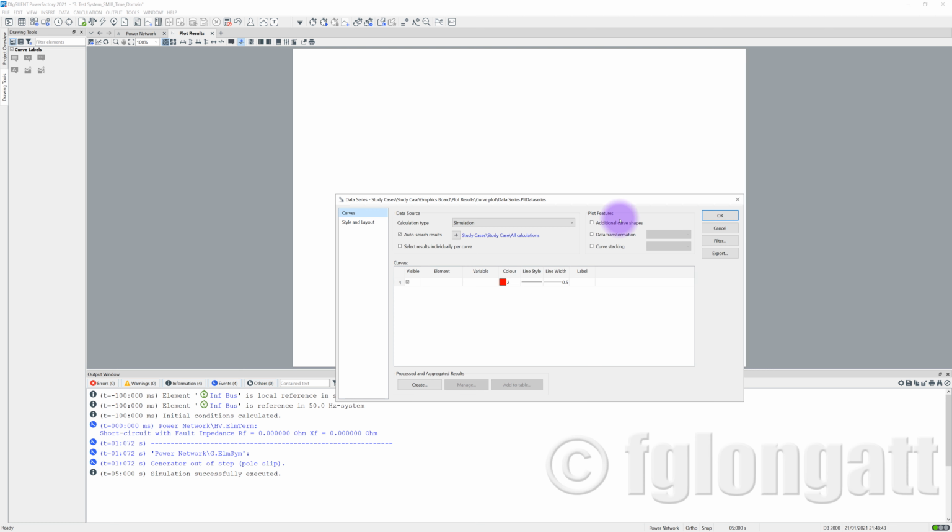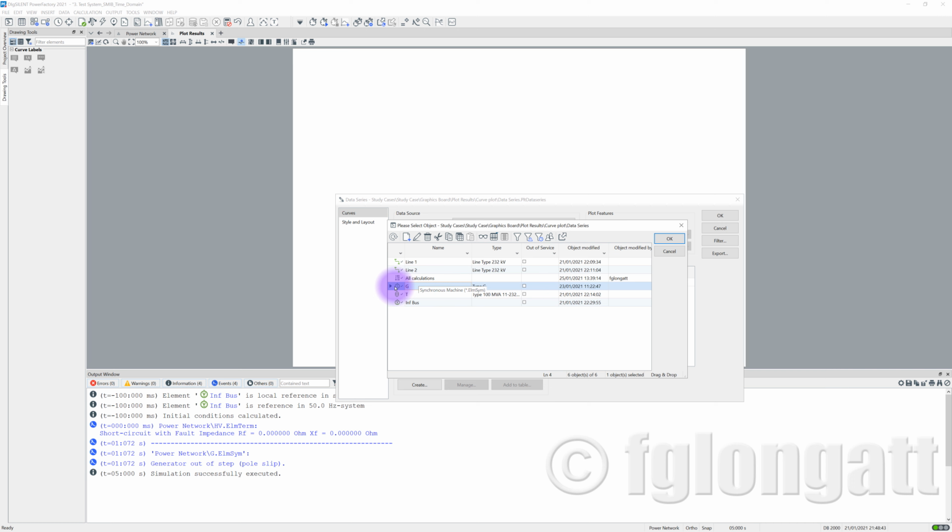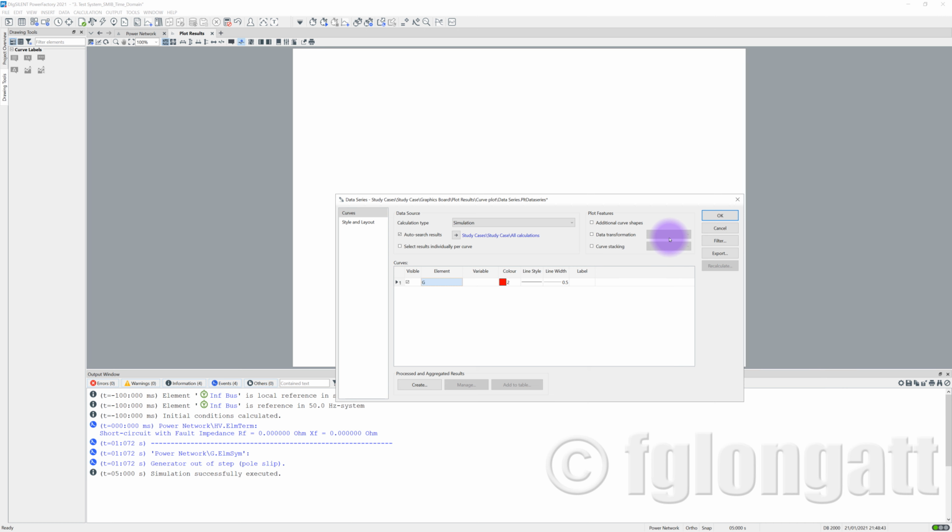When you select OK, Power Factory will come back to you and say, okay, you want to create a classical plot. And now Power Factory is asking, okay, I need to connect this graphical object with some numerical data. This graphic object must have the object name and the variable that you want to plot. For that reason, if you click here, element, I will select the generator, okay? Because we are working on rotor angle stability. I will select here the generator, ta-da! And right now you can see here the element is the synchronous generator.